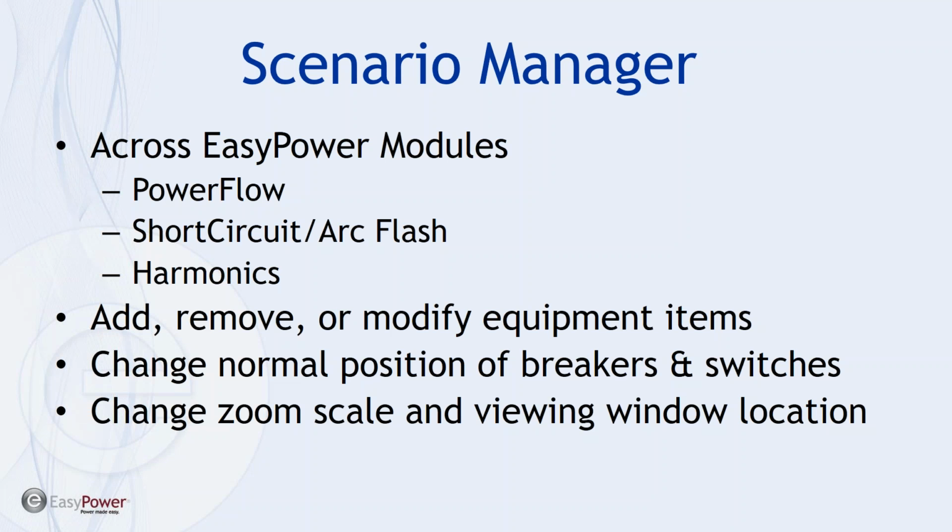Scenario Manager was developed to work with several different modules in EasyPower, including Power Flow, Short Circuit, Arc Flash, and the Harmonic modules. What it allows us to do is to add, remove, or modify equipment in the one line and then be able to compare the results and save the alternative configuration for future reference and not make any changes to the actual base case.